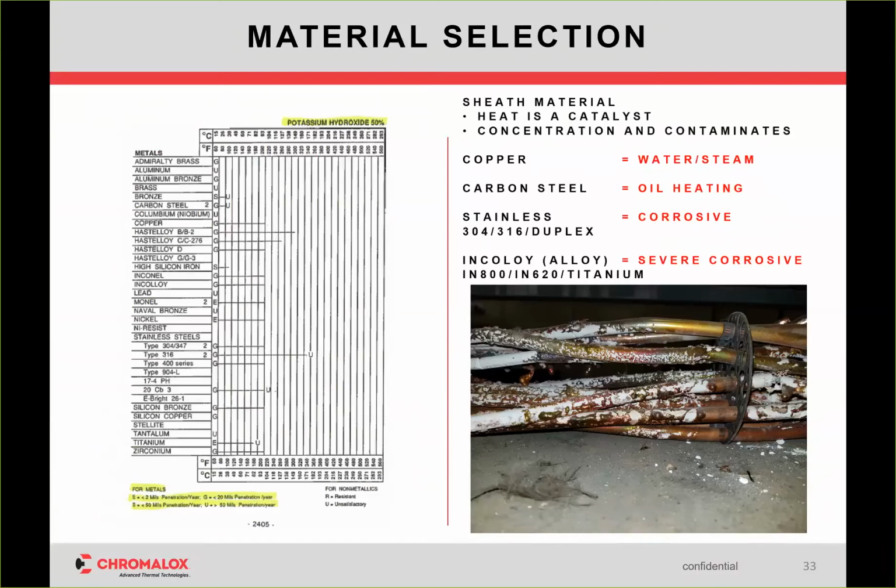I'm actually getting it electronic. I'll have it shortly, and I'll post it to the team site and give it out to everyone. This is great because it measures the corrosion or penetration of the fluid, of the chemical, acid, whatever, based on material and temperature. Back to the temperature being a catalyst. And this will tell you what temperature you're running. We may be able to even show a customer, and this example was potassium hydroxide, no, you absolutely can use 316 up until about 300 degrees. No problem. I would recommend that over 304, depending on what temperatures are running.